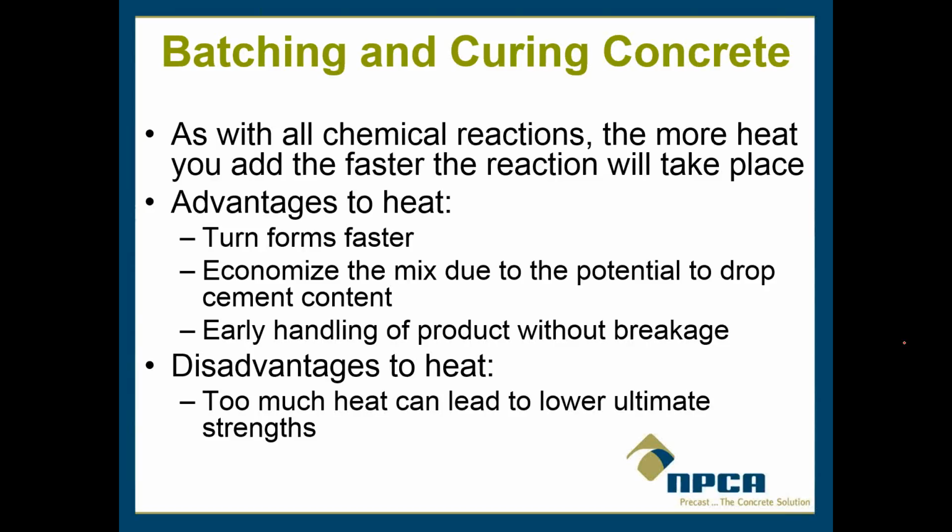So in cases like that, because we do go out and talk to specifiers and regulators, they say, yeah, we'll get somebody's product, and it hasn't cured for 28 days, so we don't know if we should accept it or not. Some of you are chuckling at that statement, but people do think that it takes 28 days for concrete to cure because of the 28-day strength that's attached to it.